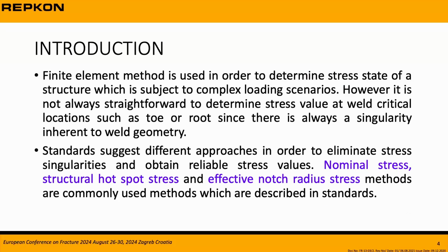Finite element method is used in order to determine the stress state of a structure which is subject to complex loading scenarios. However, it's not always straightforward to determine the stress value at weld critical locations such as the toe or root, since there is always a singularity inherent to weld geometry. Standards suggest different approaches in order to eliminate stress singularity and obtain a reliable stress value. Nominal stress, structural hotspot stress, and effective notch stress methods are commonly used methods which are described in standards.